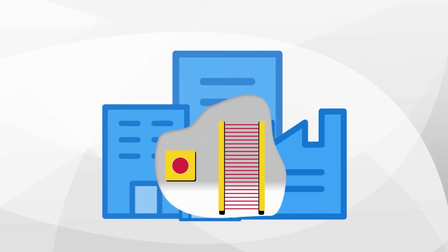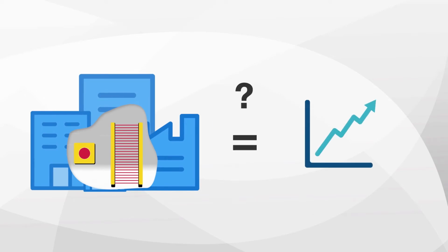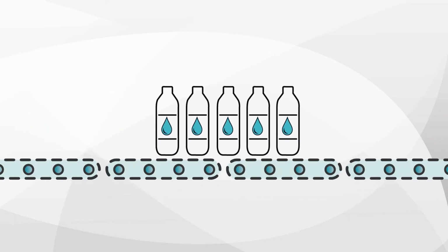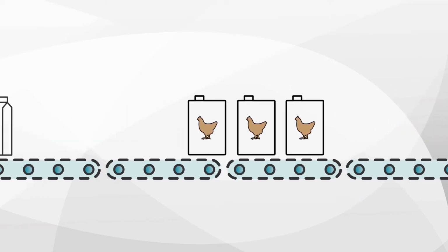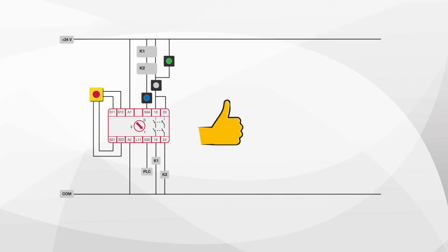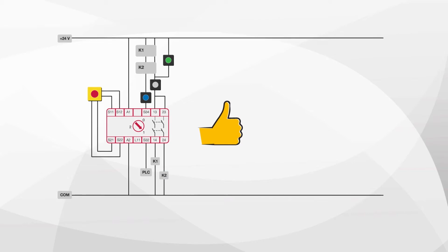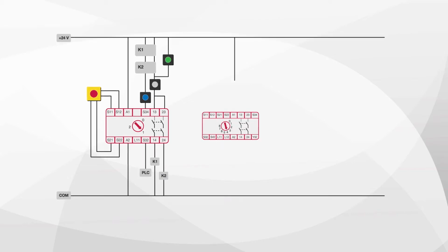Functional safety systems are common in discrete industrial applications now. But is your safety system also helping you maximize productivity? Across many industries, increased flexibility requires rapid reconfiguration of machines. Hardwired safety systems employ safety relays, which are interconnected to provide a safety function. Hardwired systems are very effective for simple safety applications.